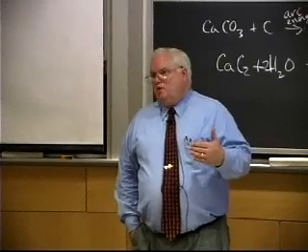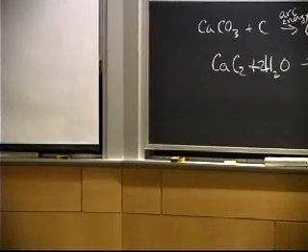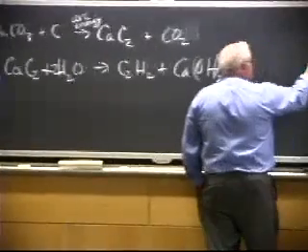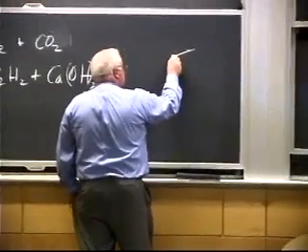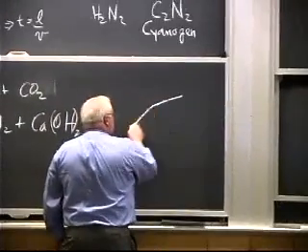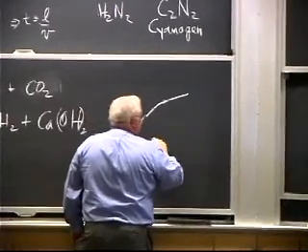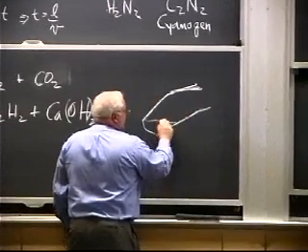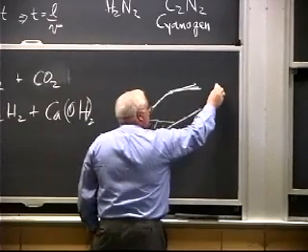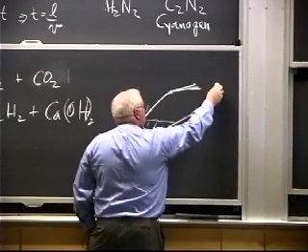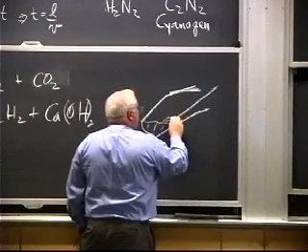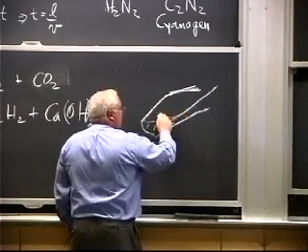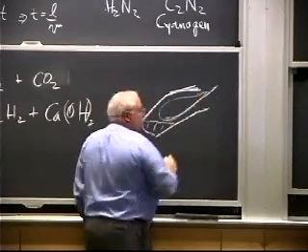And in fact, that's what Sir Henry Bessemer, whether he knew he was doing it or not, did when he developed the Bessemer converter, which is basically a vessel to melt steel that has a shape sort of like this. It has a snout on the end, and here's your steel down here in the bottom. It's a great big vessel, and you blow your air in onto the steel surface, but to get out, the air has to go back that way.